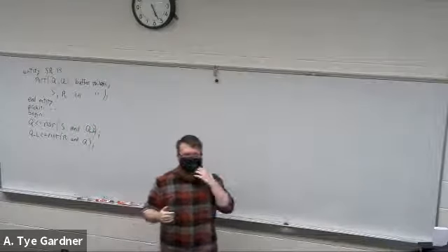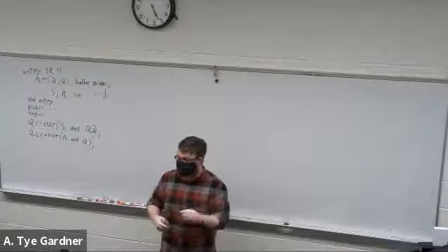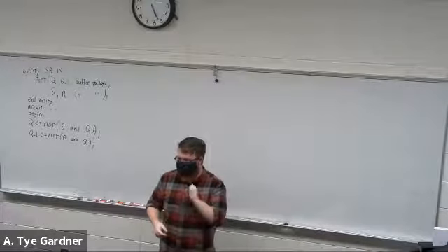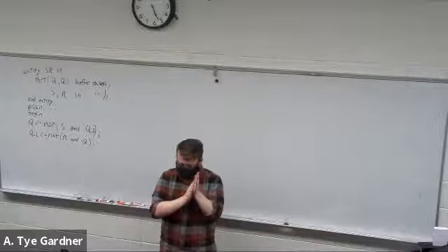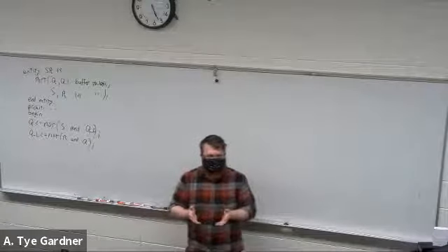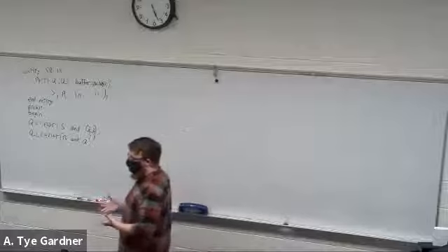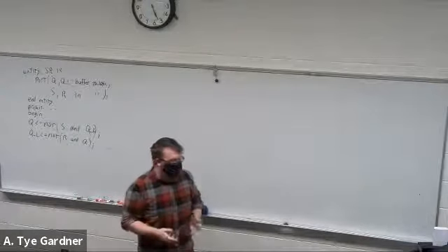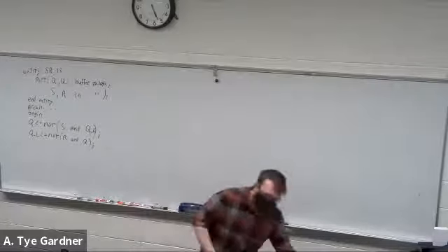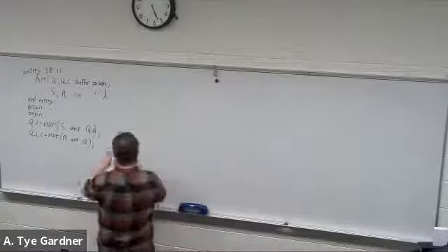Now, in a light switch, that's not an issue. But if you were throwing a switch and you wanted to count the number of times you would flick it on or off, well, I throw it once and it goes 1, 2, 3, 4, 5, 6, 7, 8, 9, right? That's a problem. We don't want that because I threw it one time. I don't want to count 9 times. So this set reset latch comes in handy.